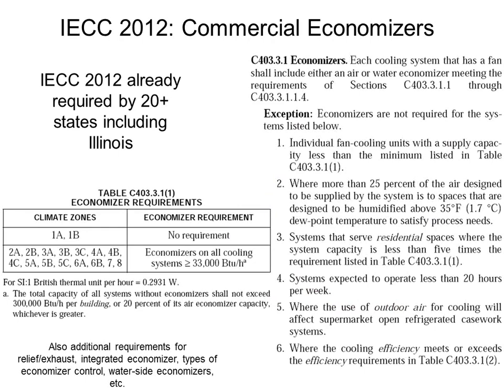For those climate zones down there, which is pretty much all climate zones except the 1 climate zones. And by the way, the only place you're going to see the ones is Miami. If you live in Miami, you can cover your ears. Everybody else got to do economizers if you're on the current code. Right? If you're on 2012, anytime you're more than 33,000 BTUs.